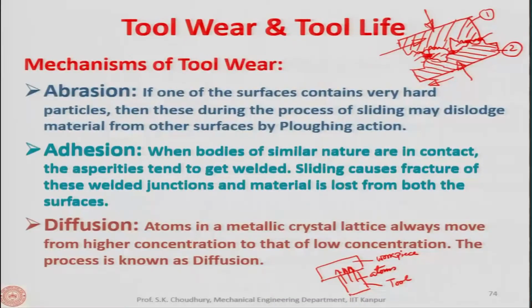In the case of welded asperity junctions, when they are broken, we said the material is lost from both surfaces, and that this mechanism is adhesion. But see, after these hard particles are sheared off, these particles remain within the mating surface.